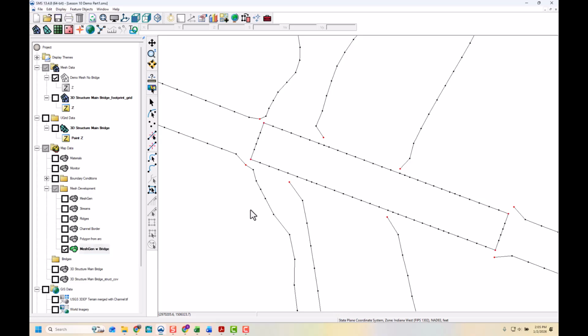And now this is what I found to be just a best practice: now that we grab each one of these nodes and reconnect them, as you grab this node and drop it, you'll see the frame forms, and that's snapping it, and it's automatically merging that. And again, I've just found this works better. Sometimes the clean tool modifies or moves things, and it's pretty critical that we leave this footprint alone so the mesh can be inserted easily. So I'm just connecting. We can connect these arcs to intermediate points. That's just fine. And we do that on both sides.